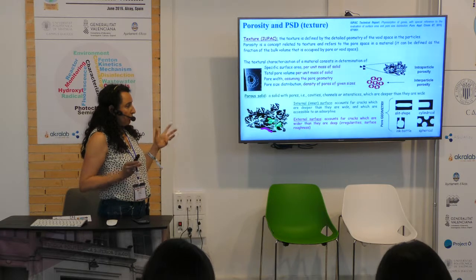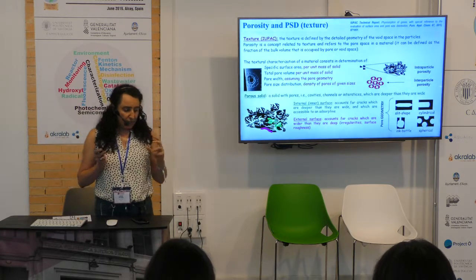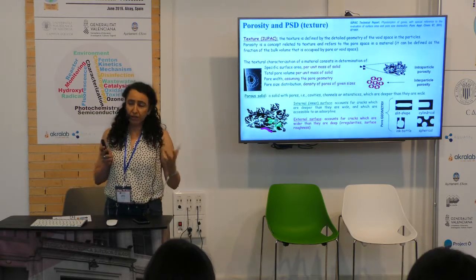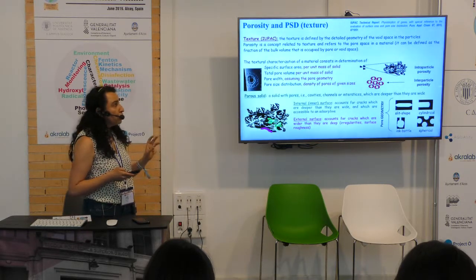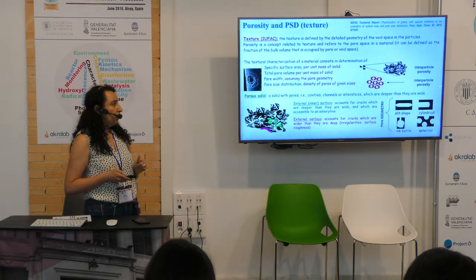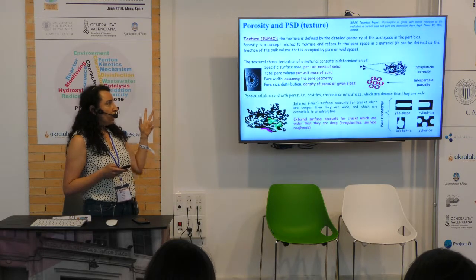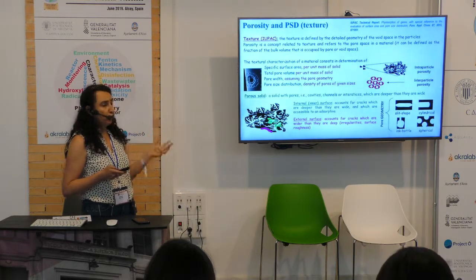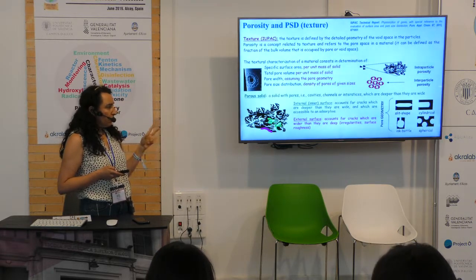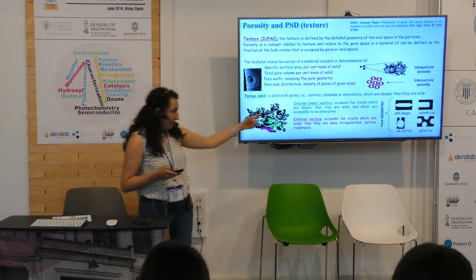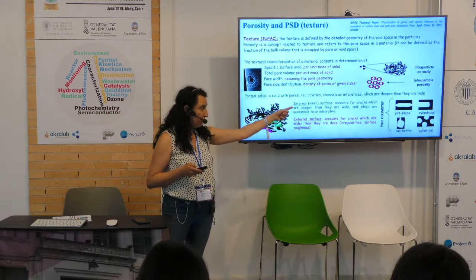When we speak about porosity, of course, what we're looking at is actually not the material itself, but the space inside the material, those empty voids in the materials. We might be interested in specific surface area, total pore volumes, and PSD, pore size distribution, as we will see. But also, particularly in catalysis, it's important to have these two concepts in mind.